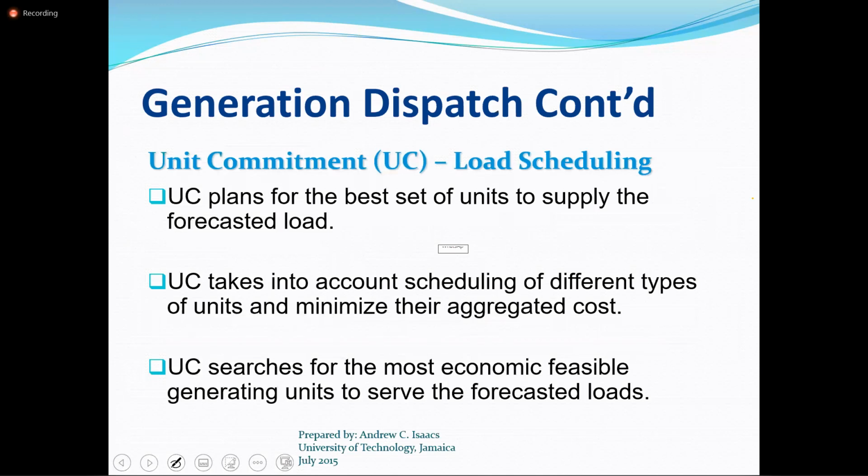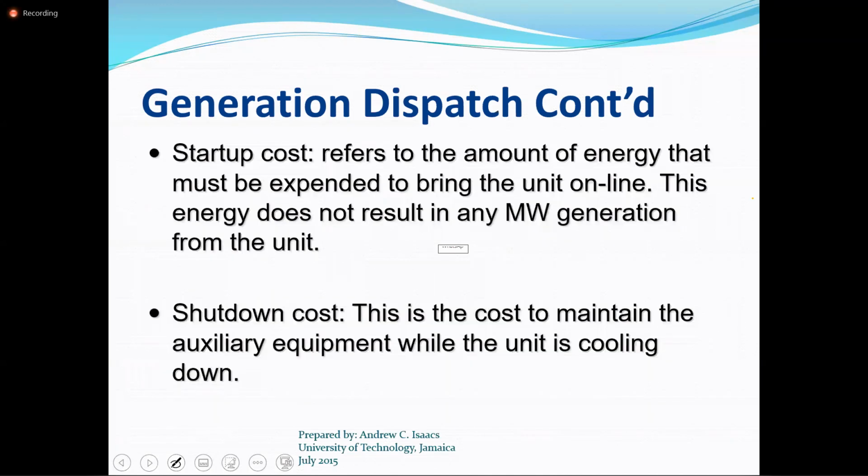By the way, the startup and shutdown costs also impact the economic dispatch, and that is built into the math. We refer to these as the fixed cost component. When you're generating 0 megawatts, there will still be a cost per hour for the operation of these units. I'll highlight that when we start doing the math associated with this topic.